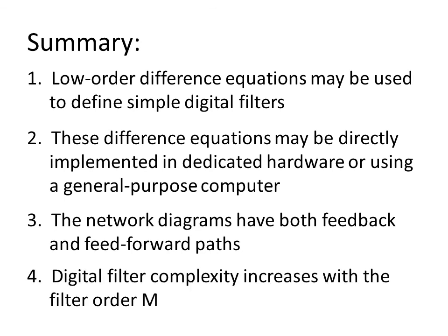And finally, the higher the order of the filter M, the more delay units are required, the more multipliers and adders are required, so therefore the digital filter complexity increases. In this lecture, we looked at simple filters having order 1 and 2. So they were the simplest possible to achieve those desired characteristics.